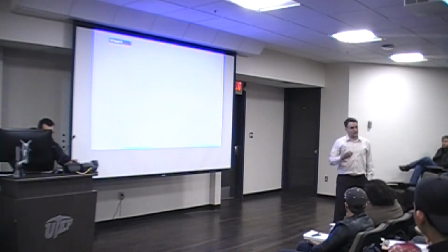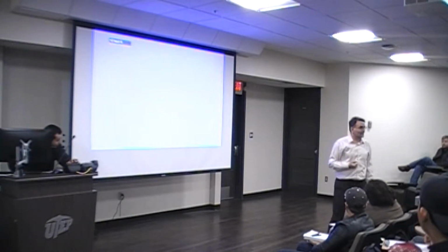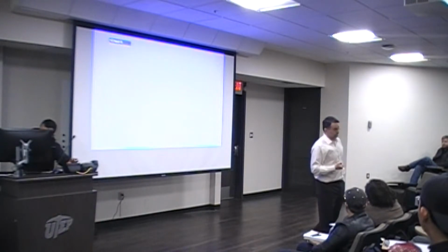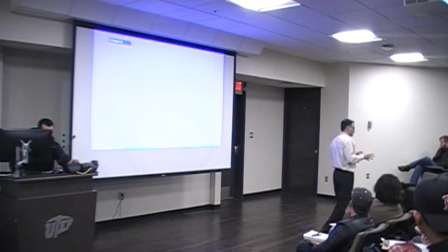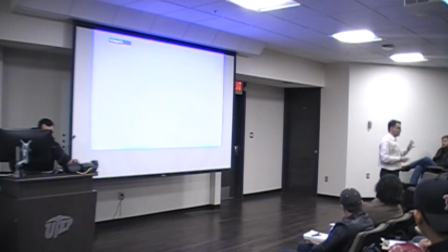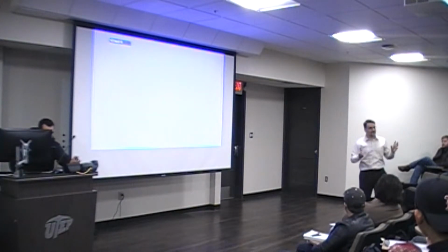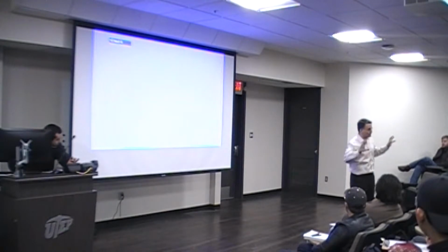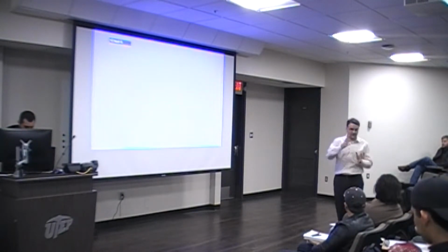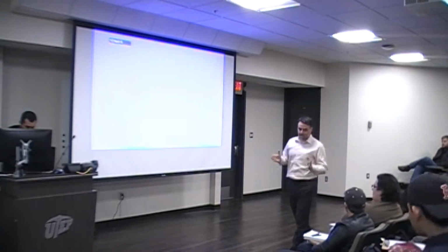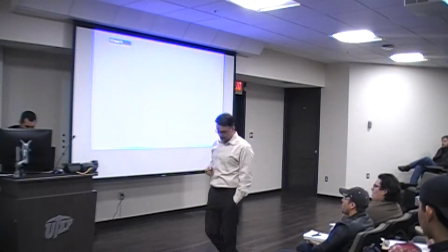What is isotropy? Yes, exactly. If you dissect the word, this is weak. Anisotropos. So basically it means non-similar properties. So the material properties are essentially different in different directions. That's basically what anisotropy means.